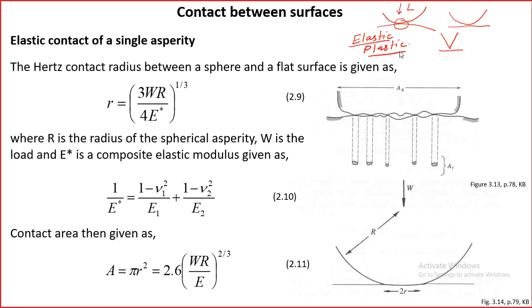So this information we will try to find out, and then our job is to find the contact area, because we have learned that contact area is very, very important. The actual contact area is not the same as the apparent contact area. For example, here in these two contacting surfaces, the apparent contact area is this one. But the actual contact areas are only some of these. Of course you add another dimension for the apparent area because we are looking at only the cross section.